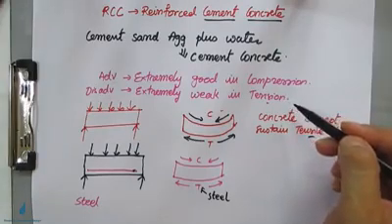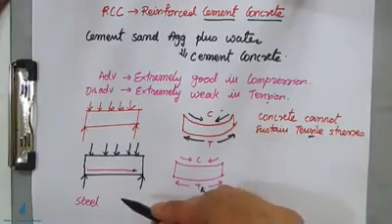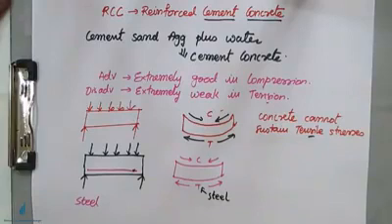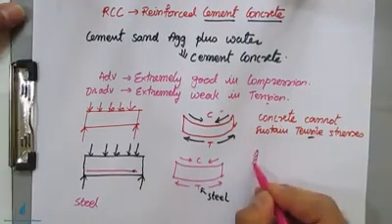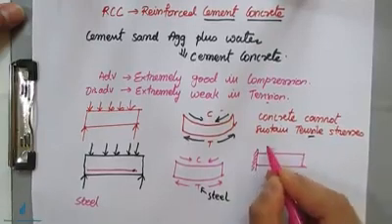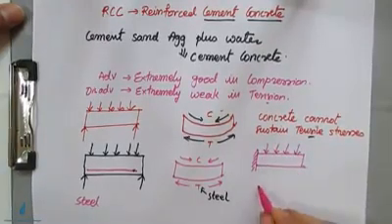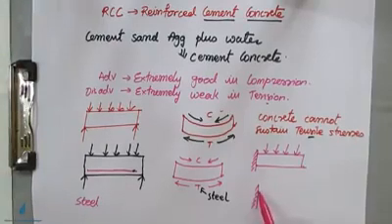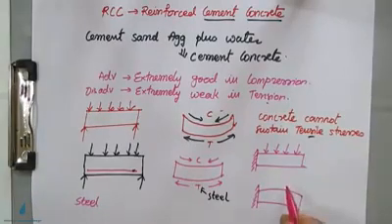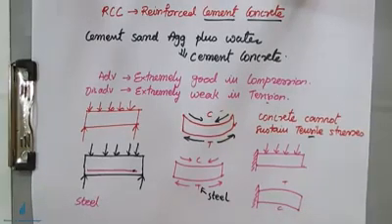But this is only with respect to the simply supported beam. Take one cantilever beam, with loads acting again. The bending pattern will change, like this. Here the upper fibers are in the tension zone and the bottom fibers are in the compression zone. This time you should not place the steel in the bottom zone. If you provide the steel in the bottom zone, it will be a complete structural disaster.